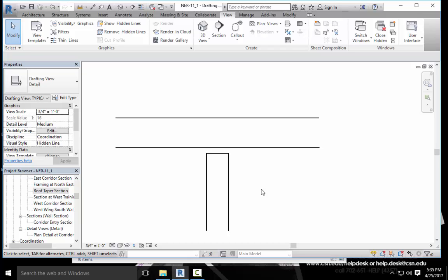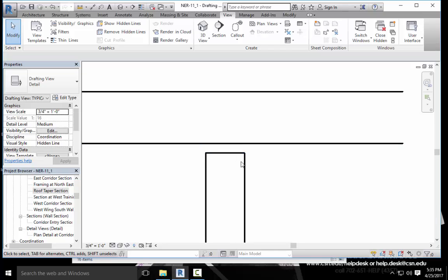The next step is to add the track to the bottom of the floor. You'll do this by creating 3 wide lines. The trick is to do a good amount of offsetting. If you want to explore and try the procedure on your own, look ahead to figure 11.57. Okay, so that's what we're going to do. We're going to look at 11.57 and go, okay. Looks like they offset 3/8 of an inch. And basically they're creating a slip track here. So we're going to do that.